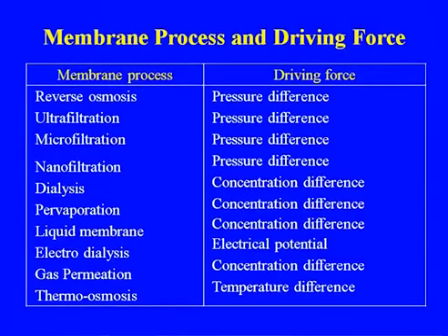Now we will be discussing the various membrane processes. As I told you, there has been continuous development in the membrane process, and so now we have a large number of membrane processes where the driving forces are different. The first are reverse osmosis and ultrafiltration, which have been used from the very beginning, and here the driving force is the pressure difference. Microfiltration, nanofiltration: in all these processes the pressure difference is the driving force.